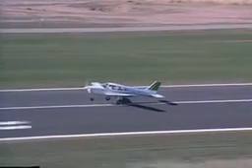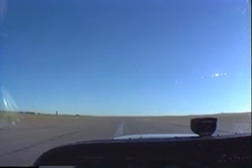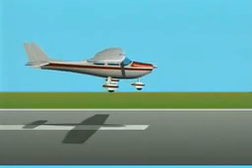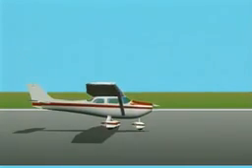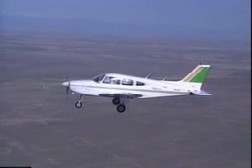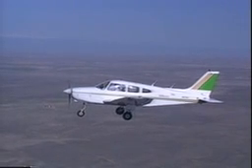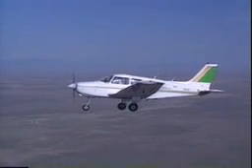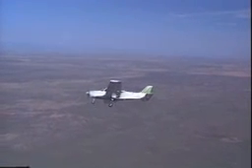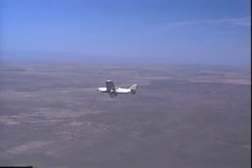Another problem occurs during takeoff, where you may lift off in ground effect at a very slow airspeed. If your airplane hasn't accelerated to a safe climb speed before climbing out of ground effect, the airplane could settle back to the runway. The information presented in this section has provided you with a fundamental knowledge of the forces at work on the airplane during straight and level, unaccelerated flight. The next section will expand your knowledge of what happens to the four basic forces during maneuvering flight.